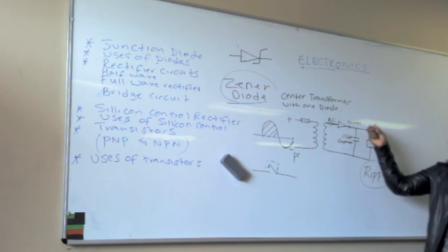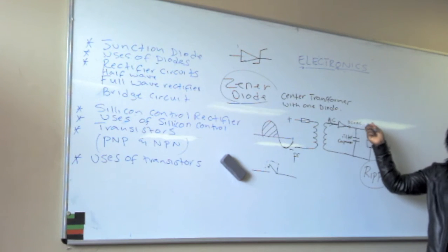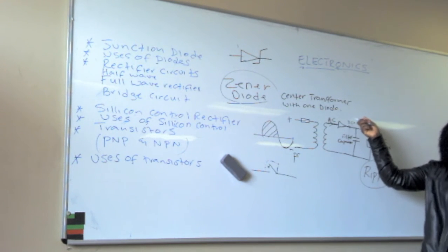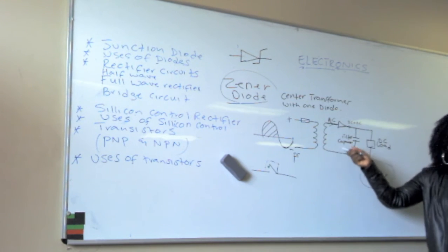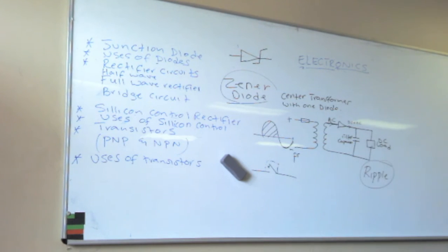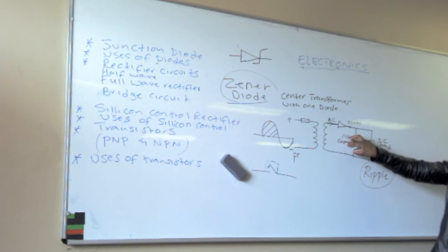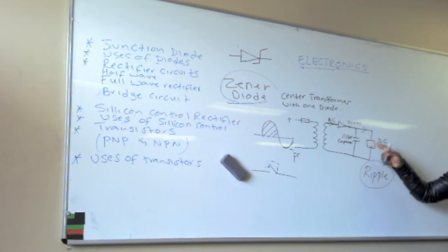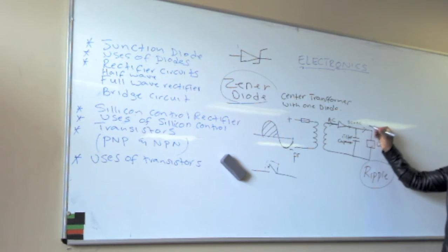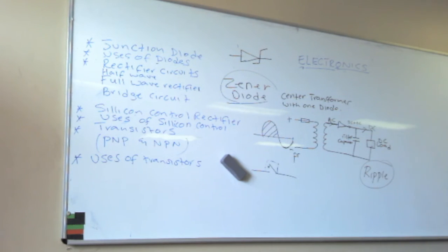So what I tell you is that when we say DC plus AC, this wave here is rippled because we have combined waves. And that is when a capacitor comes in. A filter capacitor is there to filter out any AC waves that penetrated the diode. It's filtering out, and then it stores the AC charges here. The DC charges are the charges that must be sent to the DC load. Then here we have pure DC current going to the load. So that's the system. You need to have a filter capacitor.